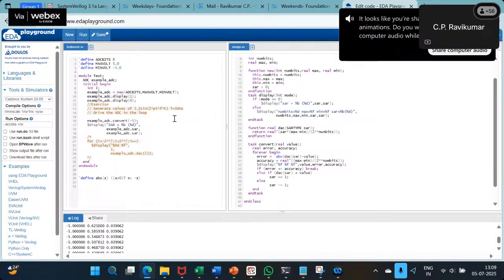By bringing in MATLAB. Okay. So plotting, I don't think is supported in SystemVerilog. SystemVerilog can, I think, plot waveforms like the EP waveform which I showed you, but analog waveforms and all it won't be able to plot. So you have to dump this data into some file and then load that into MATLAB and plot it there. It doesn't have to be MATLAB. It could be any other software that can be used to plot.